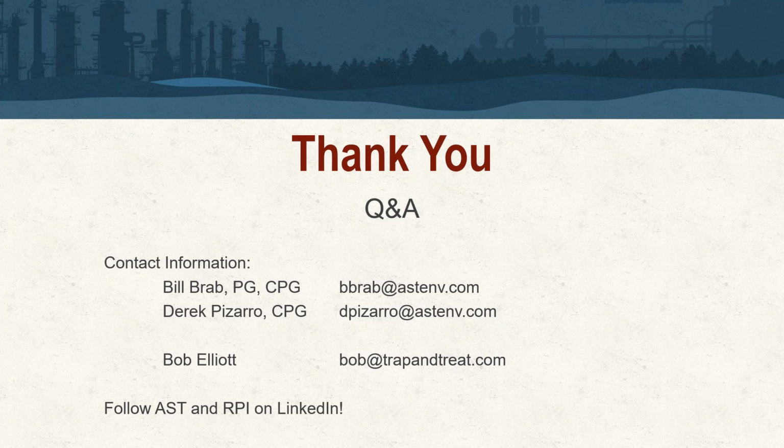Starting with the RDC that Bill and I mentioned, we're looking at identifying those intervals initially through borehole geophysics, subsequently using a discrete interval straddle packer setup to sample, if it's possible to collect water at that interval. Usually it is. Sending that sample off to RPI's lab in Golden, Colorado. They run the analysis on it that we require for our calculations. We go through that calculation process, and then we look holistically at the fracture network, the distribution theoretically across the site within that network, and then calculate loadings for each of those features, fractures.